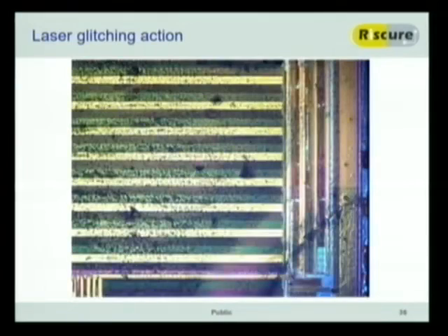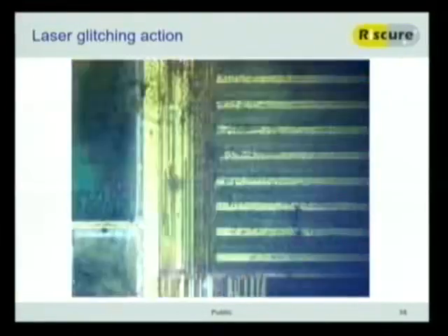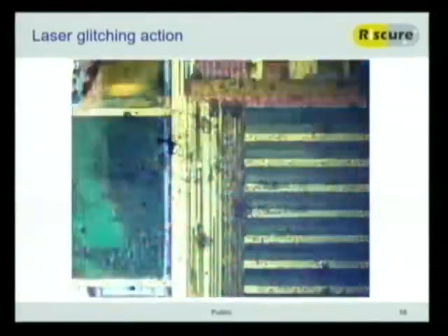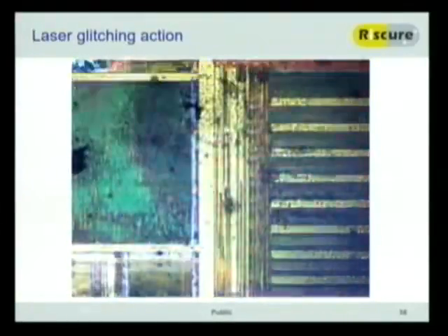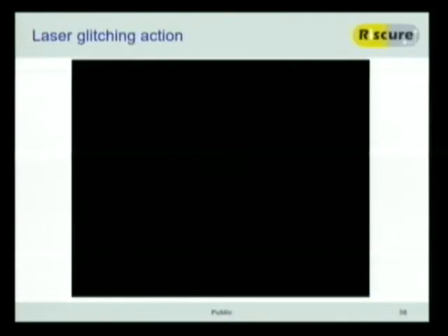Once it starts operating, it actually looks like this. You see the chip die, and it's scanning over it, and each time it sends in commands, shoots the laser, looks at the output, and tries to analyze what's going on. That's pretty cool. This is actually the same chip that you saw before. This is a little bit unrealistic. I made this for visualization purposes, because normally the laser is on so short that the camera wouldn't be able to capture it.